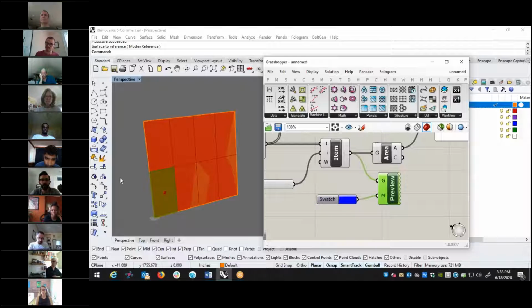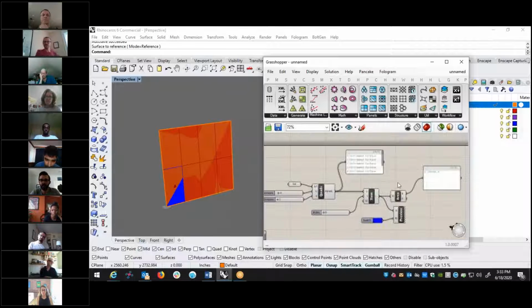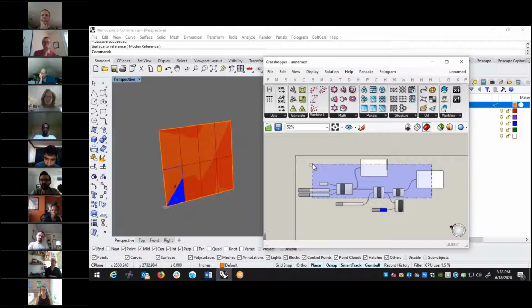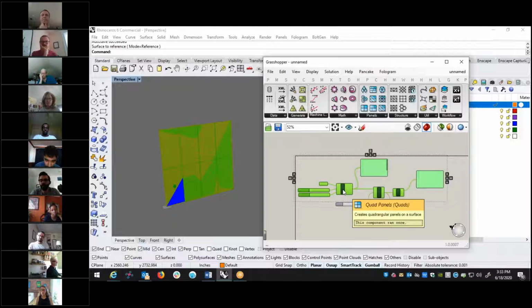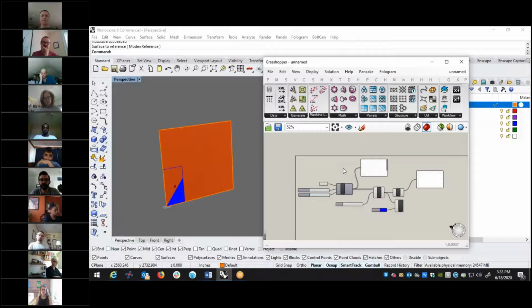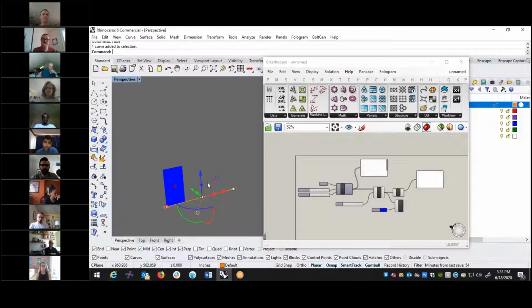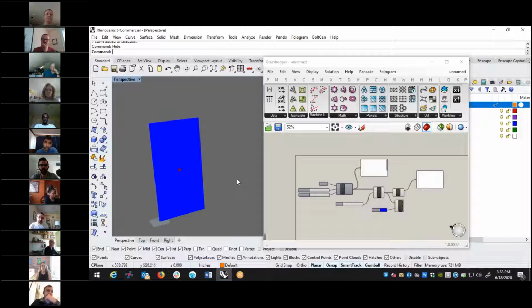And now all that is what I see. There's a lot of information in this document. I can select it all if I want. I can right click. And there's a little button here called preview. If I want to turn everything off, except for that blue square, I can even hide my geometry in Rhino. Turn this preview off as well. That's sort of what you're done.